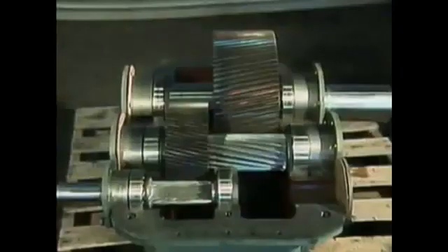A fixed coupling connects a driver shaft and a compressor shaft so that both rotate at the same speed. When a fixed coupling is used, the speed of the compressor can be changed by changing the speed of the driver. With a variable speed coupling, the driver can be operated at a constant speed, and the speed of the compressor can be changed using the coupling. A gear drive is another device that can be used to allow a compressor to rotate at a faster or slower speed than the compressor's driver.